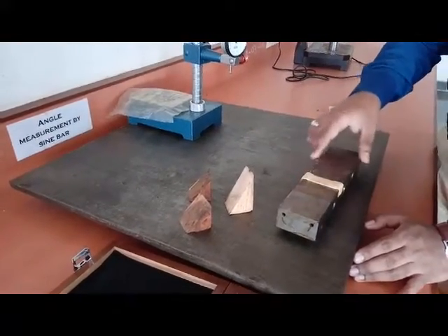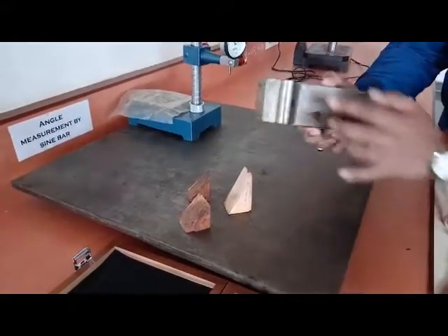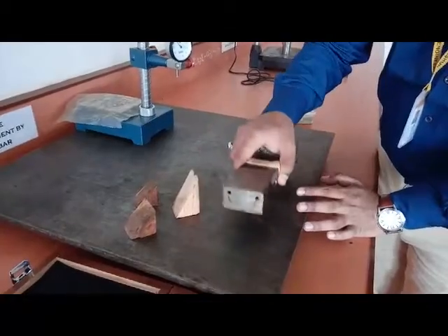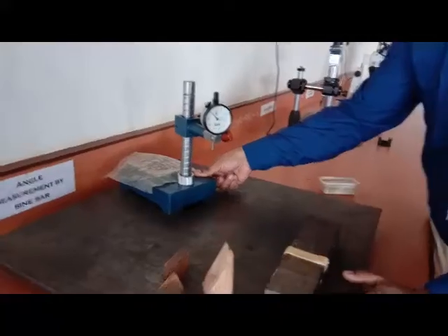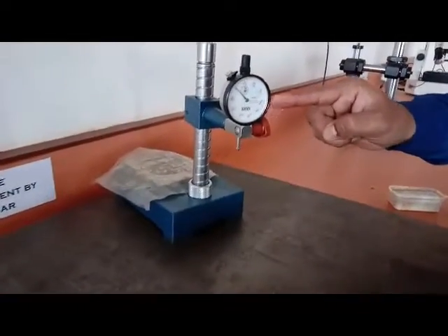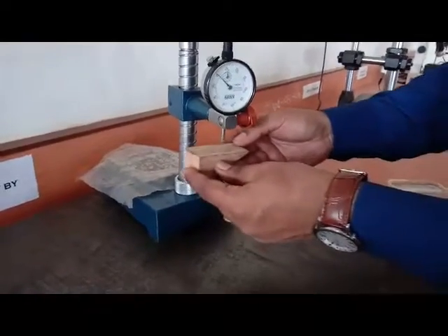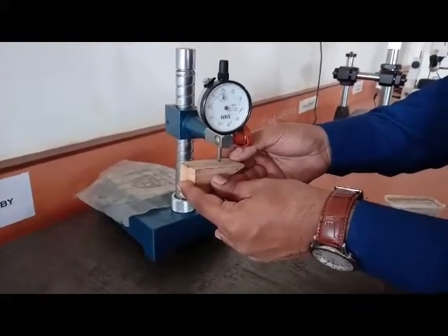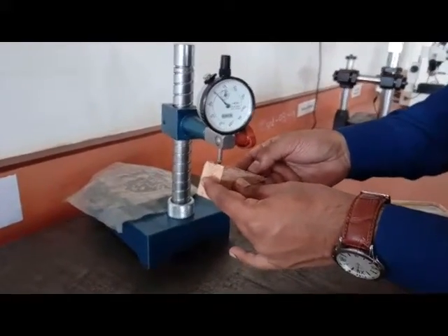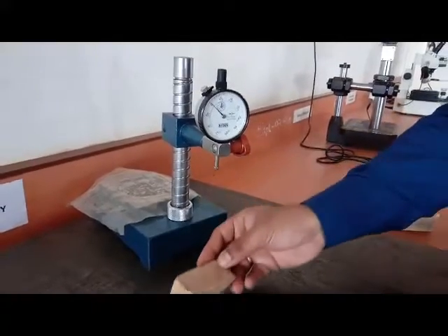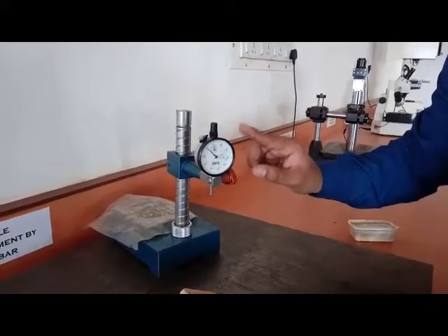Now the sine bar is made up of steel and it is lapped to the surface so that you can see it is having a plain surface everywhere. Next we require a primary measurement system called a dial indicator, for accurate measurement of the surfaces. When we touch it, it will show like this for different surfaces, and where the surface is not regular it will go beyond its original dimension. So this is the most basic measurement indicator, that is, the dial indicator.